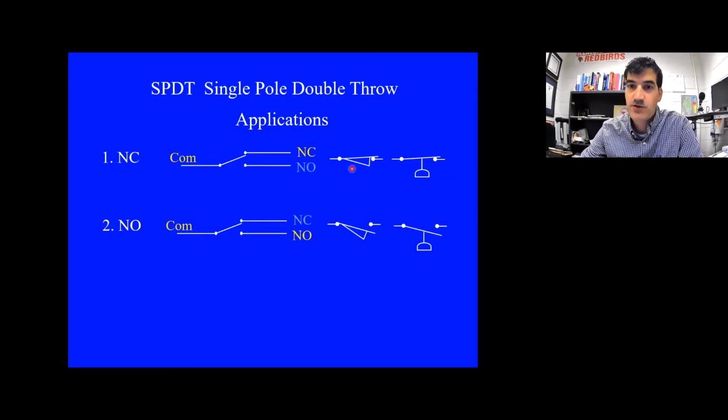So you'll see symbols for normally closed limit switches, which means that normally they conduct electricity through them unless you press on them. And when you press on them, then that moves this switch right here. And so when you press on them, then it opens the connection. So they no longer have a connection right here. So this is a limit switch, and this is a float switch. Think of like the level in a tank. As the level in the tank rises up, there's a float right here. And as the float lifts up, then it breaks this connection. It opens this connection right here.